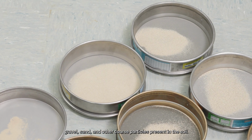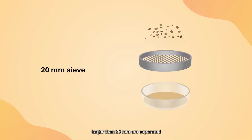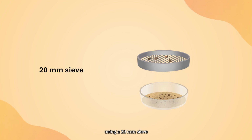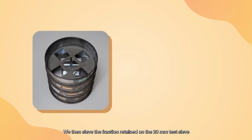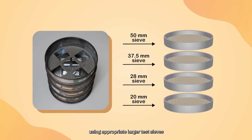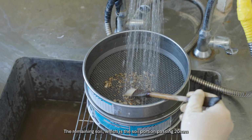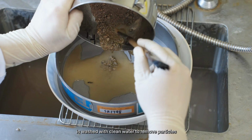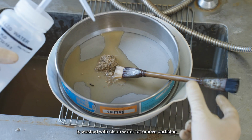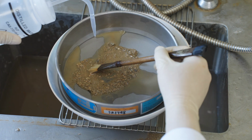At the beginning of the test, individual particles larger than 20 mm are separated using a 20 mm sieve. We then sieve the fraction retained on the 20 mm test sieve using appropriate larger test sieves. The remaining soil, which is the soil portion passing 20 mm, is washed with clean water to remove particles smaller than 63 microns and oven dried.